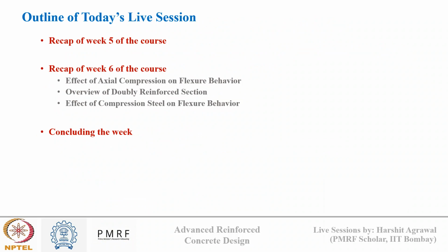So the week 6 recordings were oriented in continuation to our discussion towards understanding the flexural behavior of reinforced concrete. Okay, so in this we first had a basic overview of the effect of axial compression force and its magnitude on the reinforced concrete system, and its response to flexural forces. And then we talked about the doubly reinforced section, why reinforcement is added on the compression side, and how we design the moment curvature behavior for such sections.